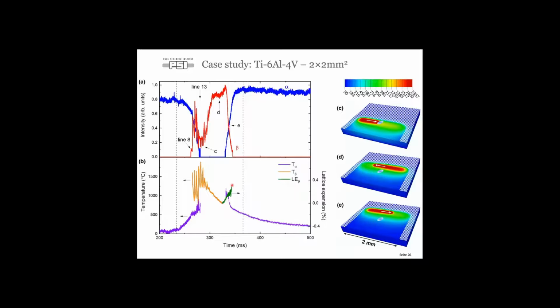You may wonder what is happening here with these temperatures. This is because when the alpha phase is growing inside the beta grains, there's a difference in lattice volume, or unit cell volume, and this creates locally some stresses in the material. So we get this artificial change in the temperature curve.